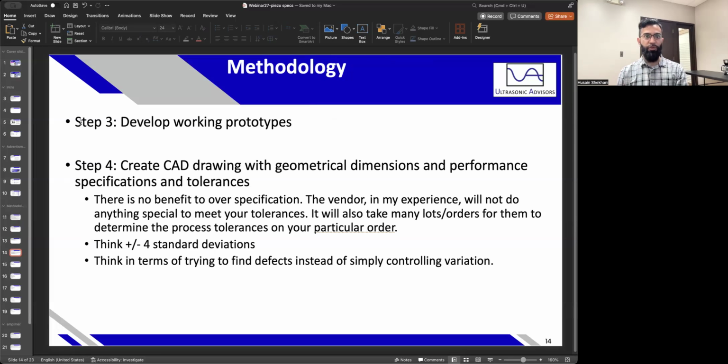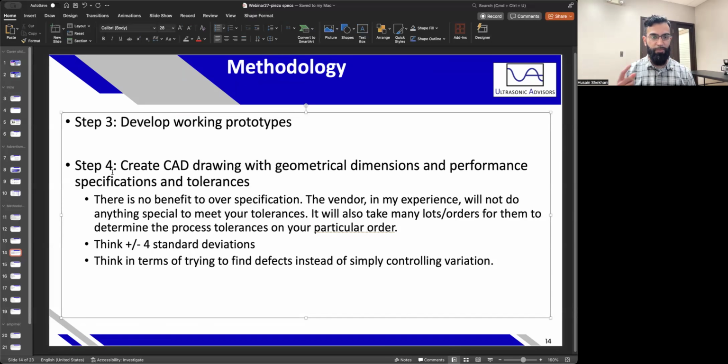After you have those ceramics, you've measured them first, then you make working prototypes. Because if you build them into the prototypes and they work, and then you undo them, either they're glued together, or if you untorque them, then they're going to be different. They may have different properties because your assembly process may have changed their internal properties, because their microstructure is, you could say, alive. The piezoelectric ferroelectric material microstructure is alive. It changes based on stress and electric field. So you may have changed it. So measure before, basically. And if your prototypes are working, that's awesome. So now you have specs. Now you have measurements of the piezos that went into your prototypes that work.